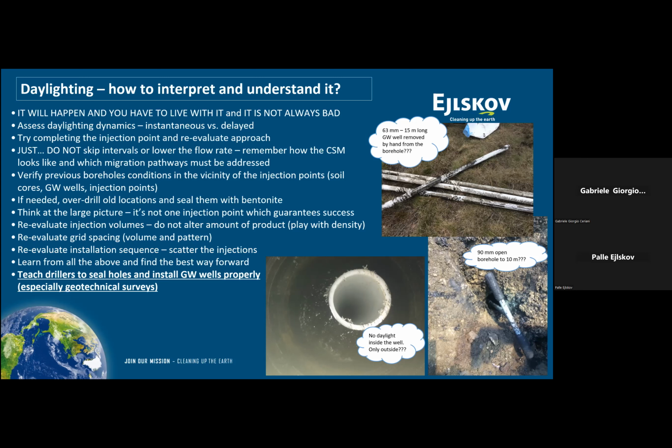You have to play with that kind of information, and you need to understand how to address it, because it's not every single injection point or every single injection interval that counts. It's the complexity and the total number of points that you're doing that require understanding when you are in the field, and how to manage that change and apply the product properly based on the CSM, the targets that you have to achieve, and the criteria that authorities and the client may have put in place. So it's a lot of experience that comes into that.